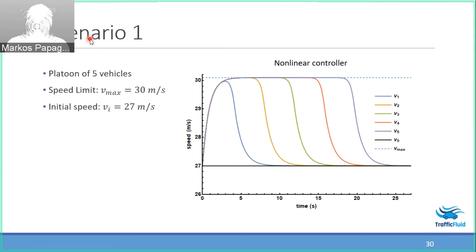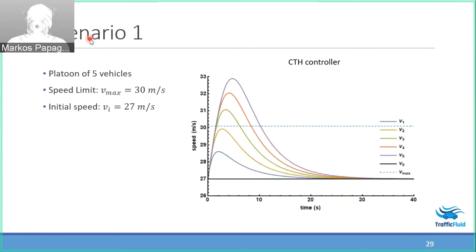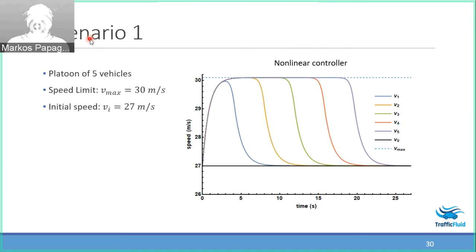Yeah, this one. The point is here that, as you have seen in the previous slide, other controllers would exceed the maximum limit and would be string unstable like this. This controller does not exceed the speed limit, but makes full use of it to behave in the best possible way. That's why it looks like it's not amplified, but it's also not lower than the initial disturbance. It stays below the speed limit, and that's the reason why it looks like that, and certainly it is string stable.